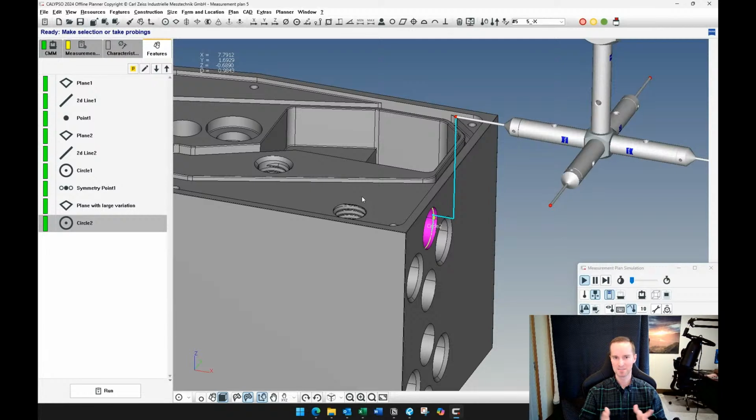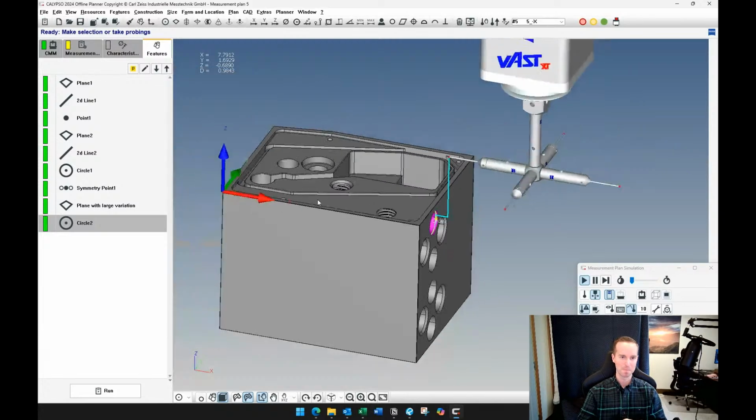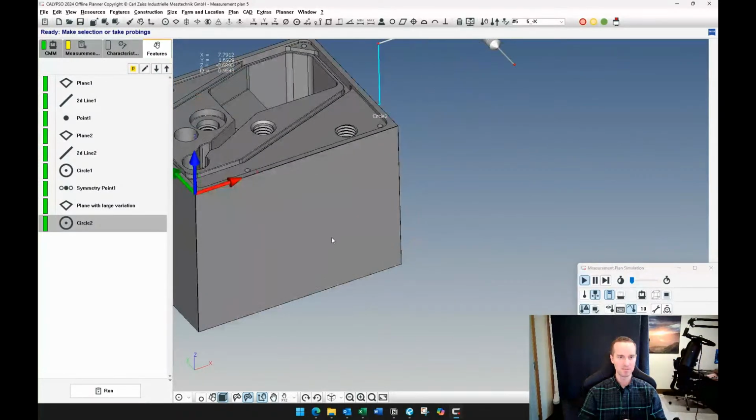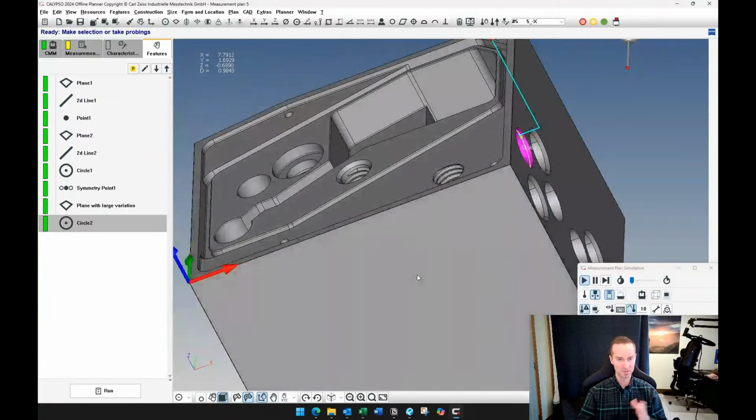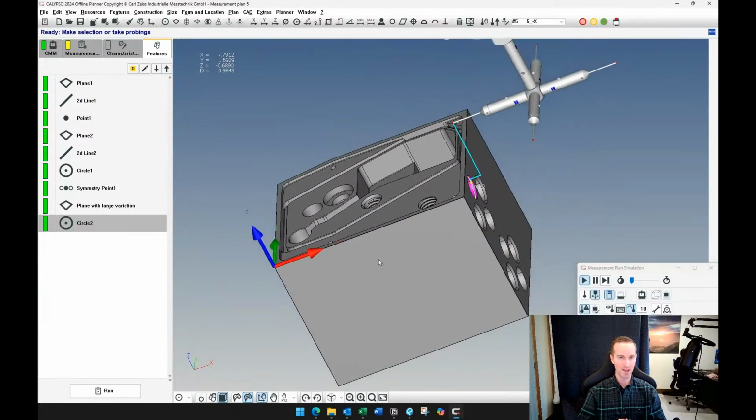It explains the difference, with a simulation example. But hopefully that clarifies to you the difference and why you need clearance distance in some cases. I actually do set most of the time the clearance distance to 0 and just handle the real clearance or the retract just with the retract distance.